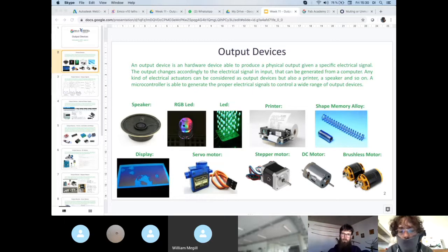By this possibility of controlling the position of the shaft, you can enable a lot of different applications. For instance, all the digital fabrication machines that we have in our Fab Lab, such as 3D printers, laser cutters, CNC machines, and so on, use this precise positioning of the shaft, in this case of the stepper motor, to determine the position of the machine, or to determine, for example, the distance that one axis has to move to 3D print or to laser cut or to CNC mill something. Thanks to this positioning, the machines are able to produce something precise.